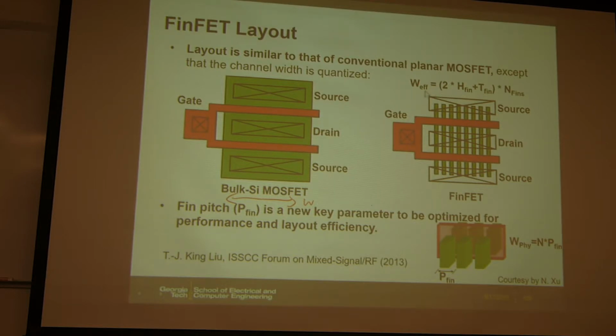And the effective W here, as we discussed, each fin will give you 2 times h of the fin plus the t of the fin. So that is the electrical or effective W given by each fin. And then you can tune the number of fins.